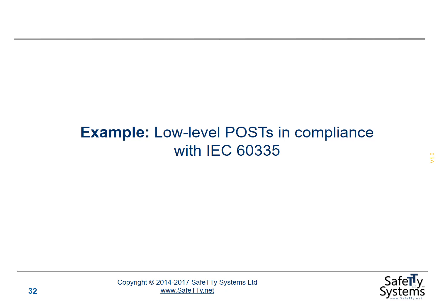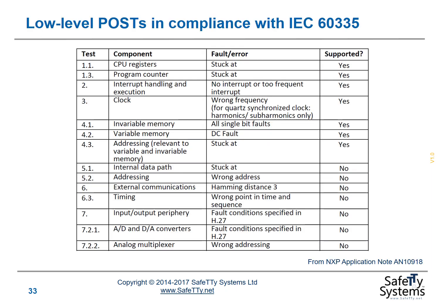As an example, there's a code library available that supports power-on self-tests in compliance with IEC 60335. This table is taken from NXP application note AN10918, and this shows the support provided by this particular library for this particular range of microcontrollers. Similar libraries are provided by other MCU manufacturers. You may like to take a look at the related application note for further details.